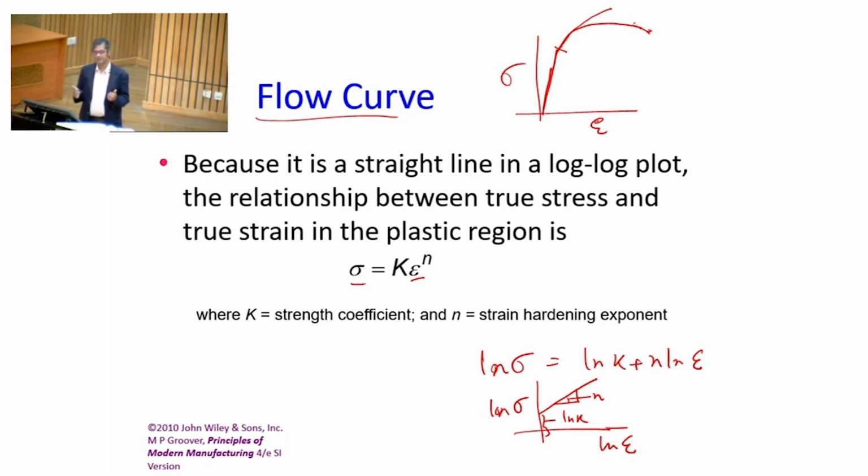So, therefore, it is a fraction, okay. And hence this relationship between sigma and epsilon is very dependent on this parameter n, because the n value changing will lead to a significant change in the flow curve. So, you must remember that we can always determine the value of n by simply taking a log on both sides. That is what is shown in this derivation.